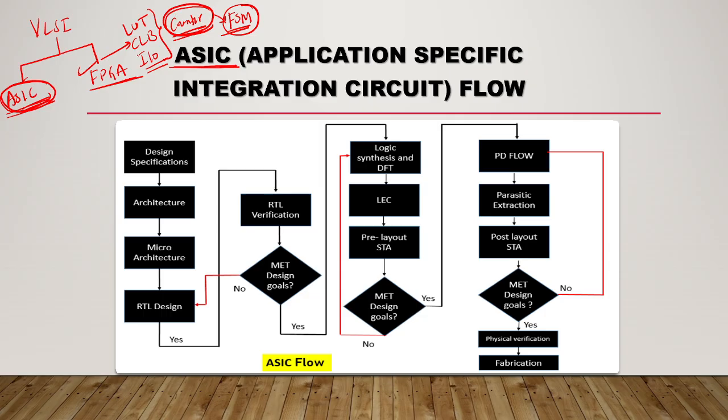So that means you can erase the program. Okay, so mainly it consists of some SRAM. Okay, this is volatile, as long as the power is there that we are using, and mainly this is used only for the R&D purpose. You have FPGA boards like Xilinx boards, Altera boards. With the help of those boards, you are loading, you are porting your design into this FPGA, and you can use it for R&D purpose.